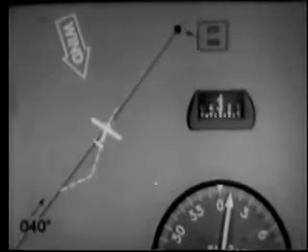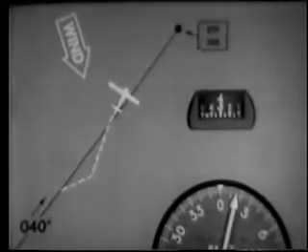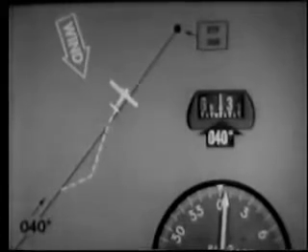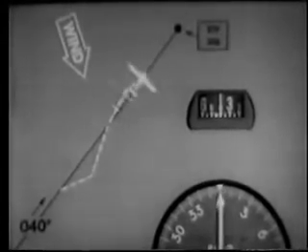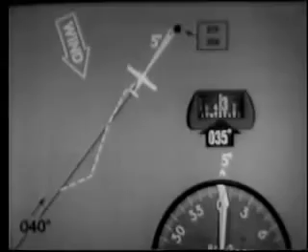Suppose after trying our first 10-degree correction, the needle moved to the right. In this case, we would have known a 10-degree correction was too much. To correct this, we turn to the inbound heading of our track, 40 degrees, and let the wind drift us back to the track. At this point, we would turn to a heading of 35 degrees to establish a new trial correction of 5 degrees left.